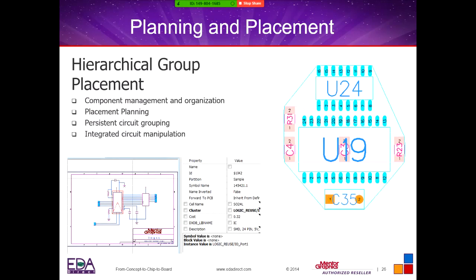You'll also have hierarchical group placing. So if you have hierarchicals that you've laid out in the schematic, and you need to push into those, we can do that in the schematic, and as well, we can use our group placement planning to bring, if you have like an I/O section of a design, all the components on there.